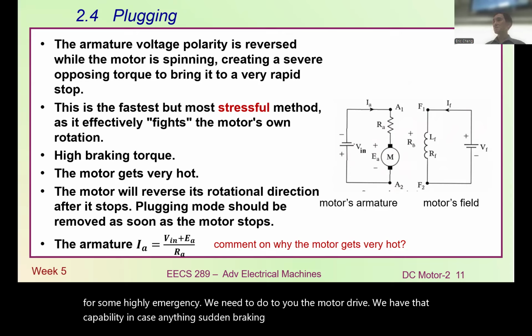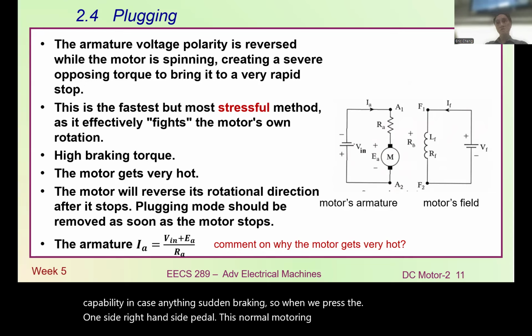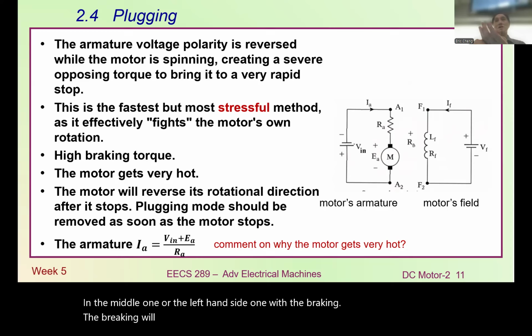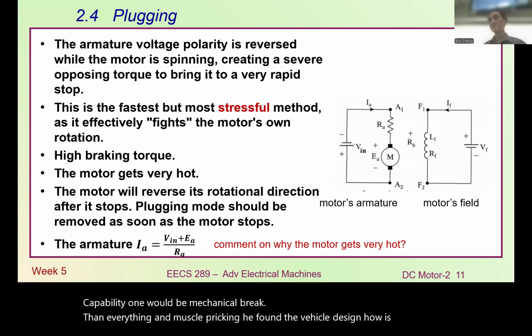So when we press the right-hand side pedal, that's normal motoring and regeneration. And the middle one, or the left-hand side one, is the braking. The braking will have three kinds of capability: mechanical brake, dynamic braking, and also plugging, depending on the vehicle design, how you design it.